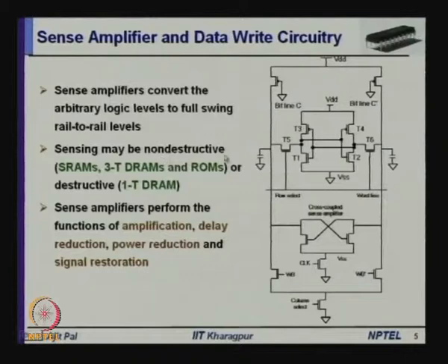As a consequence, it is non-destructive, and as we shall see, not only in SRAM, there are other types of dynamic RAMs where this sensing is also non-destructive. However, later on we shall see it is destructive in the one transistor dynamic RAM, which I shall discuss a little later. So, I shall not come to this topic once again, but that is why I am covering this. This part is different for different types of memory devices. This is for static RAM and other types of RAMs. This part will be different, but the sense amplifier and other parts will be the same.